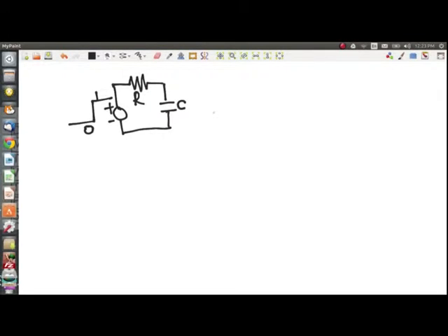So we know that a capacitor, when it is in steady state, so basically if it is a DC, the capacitor is an open. So let's see if we can predict something from that. Before this change, let's say this is at time t equal to 0. It's just a reference, saying this is when something changed. It could have been at any time.